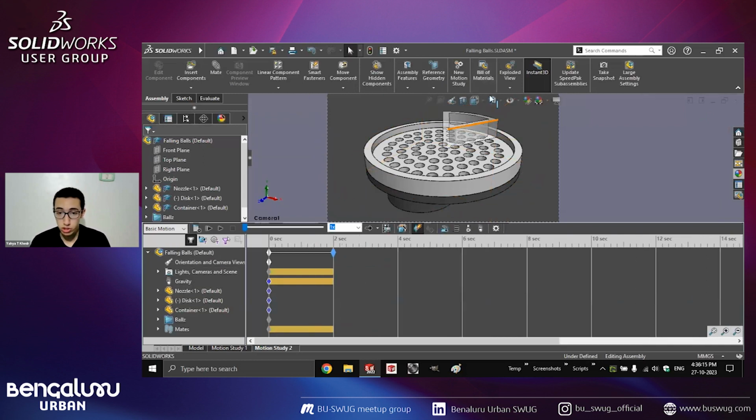So I've got the balls somewhere at the top, and I want to see how they are going to interact with my model. There's nothing actually going on, but if I step frame by frame, I can see that the balls are actually moving, but they just go through my model. They don't interact with anything. So even though I've got the gravity component correct, what I don't have right now is contacts. So I have to make these components collide with each other and stop each other from moving.